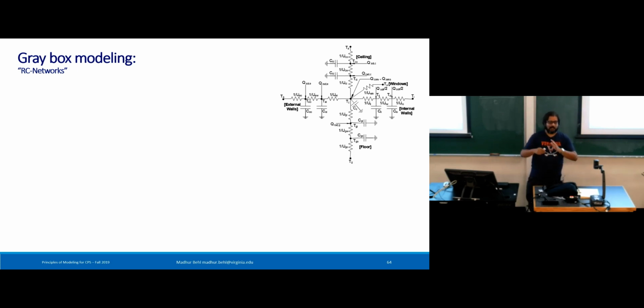Why? Because our ultimate objective was to control for demand response, to ensure thermal comfort, right? The whole reason why we wanted to predict stuff was that we wanted to be able to control the set points of the HVAC to guide the temperature in a certain trajectory or a desired range so that the electricity consumption is temporarily reduced if we are talking about demand response, right? So again, to refresh and make connections to this whole idea of model-based control, which is what motivated us to create this model in the first place.